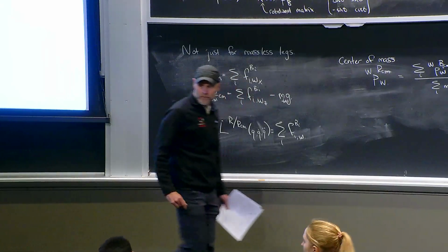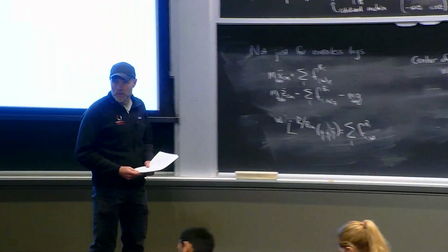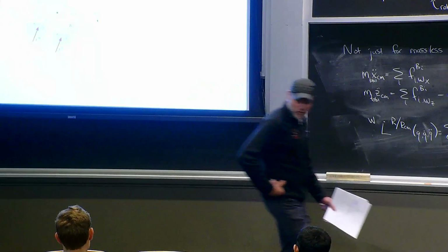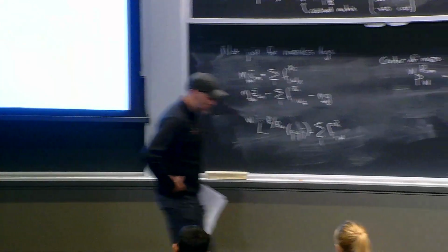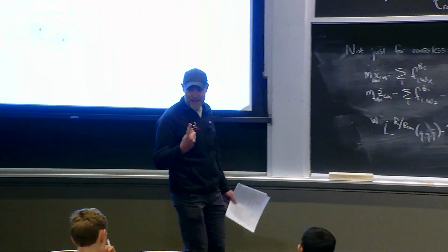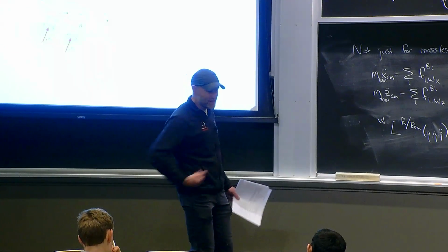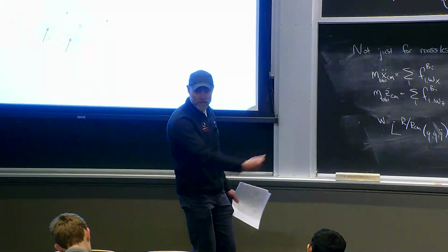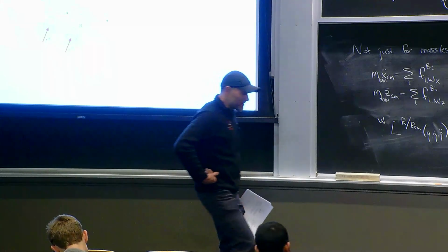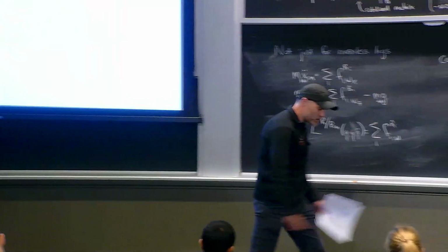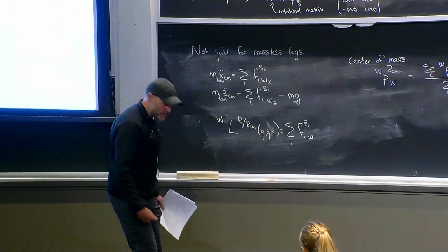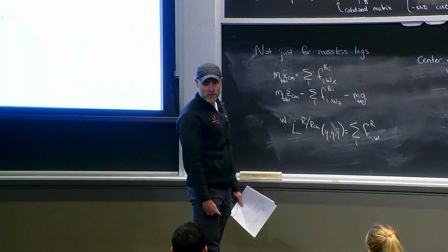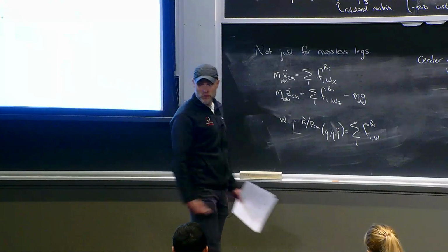Yeah? I would say he always looks like he's squatting. So why do the robots walk like this? There's 2 reasons. One, it makes the math easier. You can ignore impacts, and with small angle assumptions you can do a lot of planning with linear dynamics. The other is that the assumption that you can move your feet is better when you are not at a kinematic singularity. As soon as your leg goes straight, you have more constraints on what you can do with your feet.